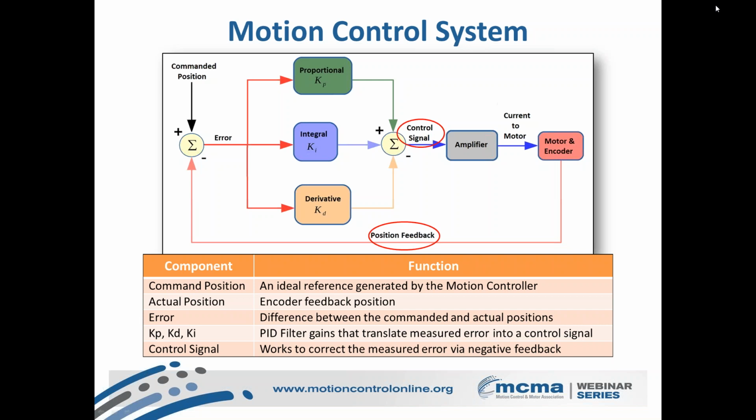And lastly, changing components, changing out a drive, is slightly complex in that in order to do so, you need to make sure that the new drive's internal circuitry is compatible with the old drive, essentially, so that the command signals and encoder signals that are being taken in and put out are comparable, so that the controller can interpret and command it appropriately.